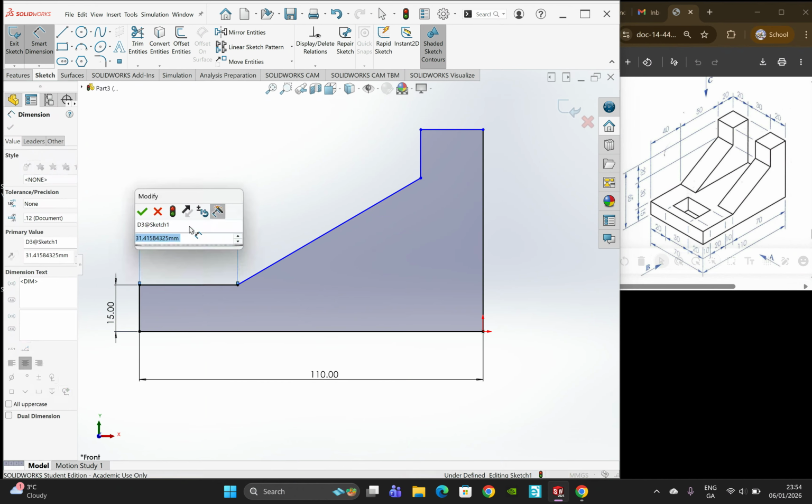So now that we're on that back surface and we're sketching, I'll just show you again. I'll click the back surface and click sketch. I'm going to go and get a corner rectangle. Start up here on the top edge. It'll go kind of orange when you're on the line. Draw it down until it kind of maps onto this line here. Don't go beyond it. Try and stick it onto the line. There we go. Now go Smart Dimension. The distance from here to here is 20. Click again. So you have to click 3 times.